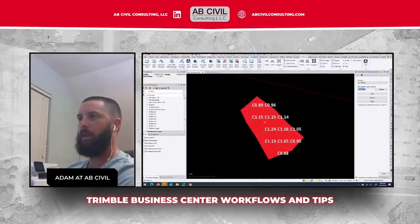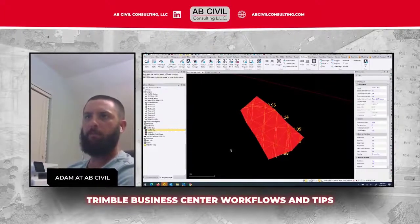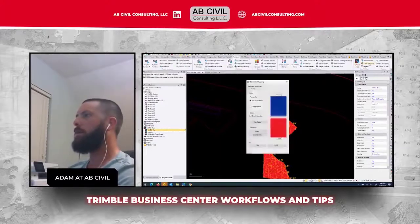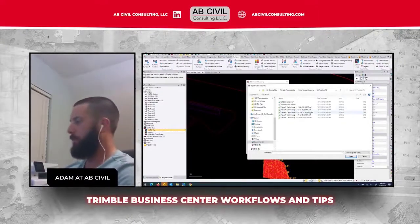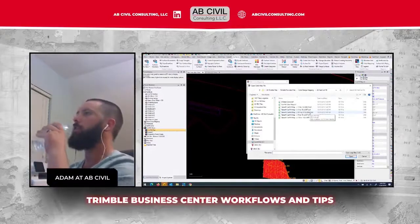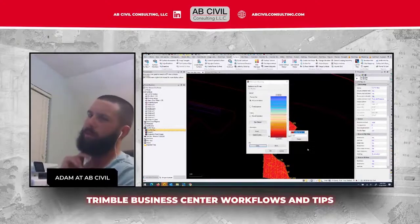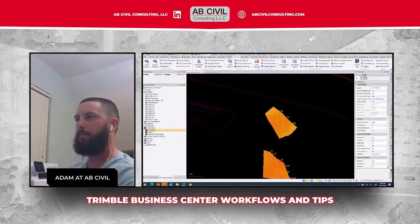So I'm going to select the cut fill map. Easier said than done. Foolproof way: go to Project Explorer, click your cut fill map, and then go up to surfaces. I'm going to go to color mapping. Then I'm going to hit load, and I got these from Trimble at some point. I could share them, if anyone else wants to use them. I just always hit this 31 base colors, hit open, then it divides it up with this color scheme, which is a lot easier on the eyes than the default. So I'm just going to hit OK.